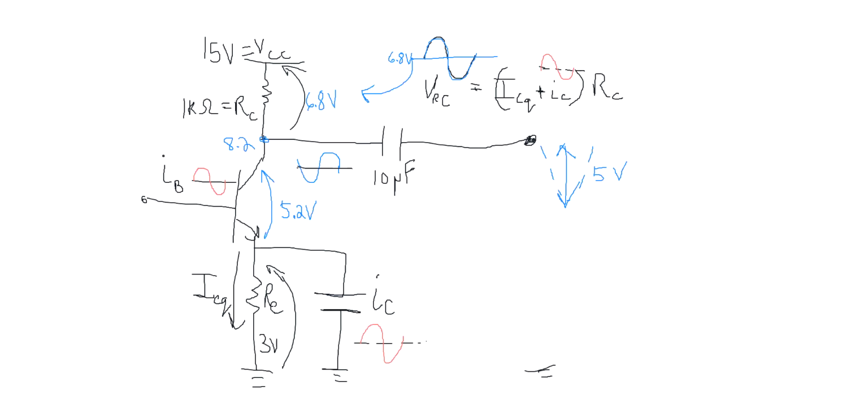Now I'm going to continue to change my base current. I'm going to go back down. My base current is going to now go to 0, which is my quiescent point. I'm back at 8.2 volts. That's right here, 8.2 volts. And I'm going to drop my base current so that I am choking the collector current. I'm decreasing my collector current. That's going to decrease my voltage across the collector resistor. Okay, you see the decrease right here, which increases the voltage across VCE.